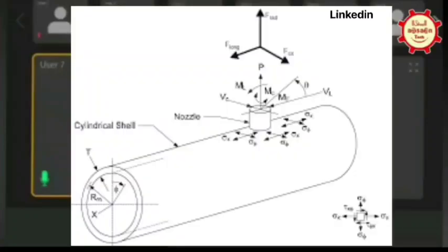Yeah, further extending that question, I applied those nozzle loads for doing derating of the nozzle curve. For derating, there are so many methods. Let us take the example of UG-44B. While using UG-44B, there are two inputs required: one is the force and the second one is the bending moment. When we have the split, expansion loads are different and sustained loads are different.